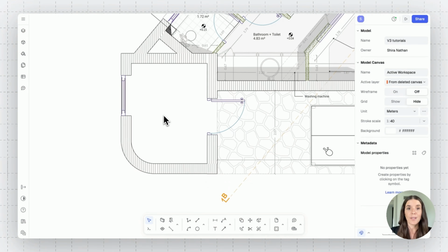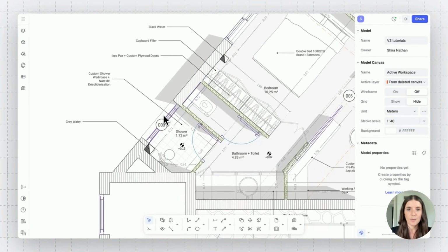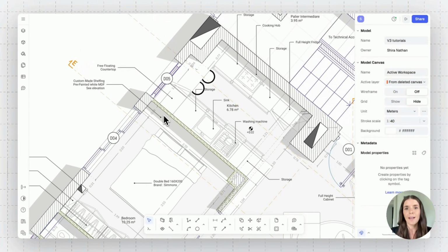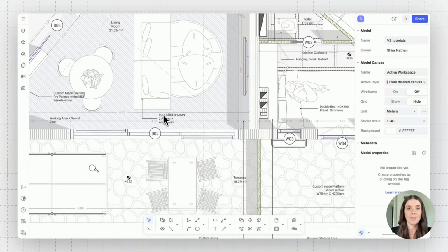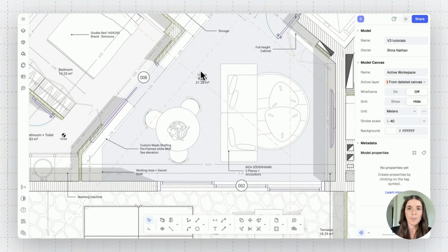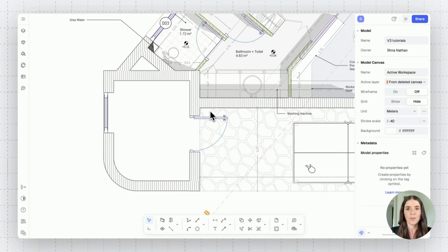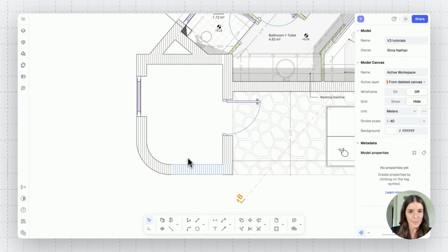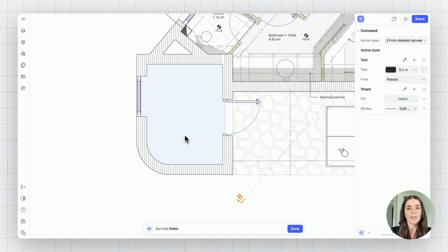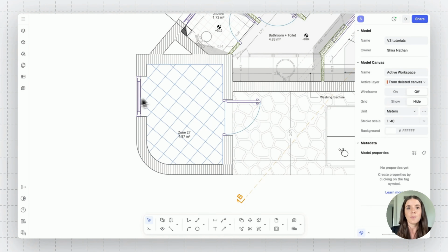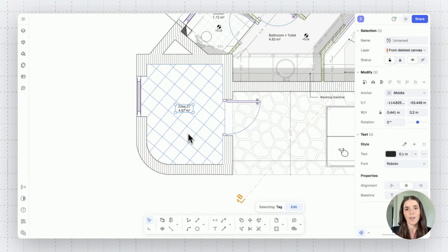The next thing to talk about is zones. Each one of these rooms you see here in our floor plan has a zone placed within it. And this is a good example. You see the highlighted blue part with this living room tag is a zone. And let's add a zone into our room right here. We're going to grab a zone from the bottom toolbar and click within a wall enclosure. This will automatically detect the shape of our wall enclosure and generate a tag with a square meter count and the zone's name. We can do a few things here.